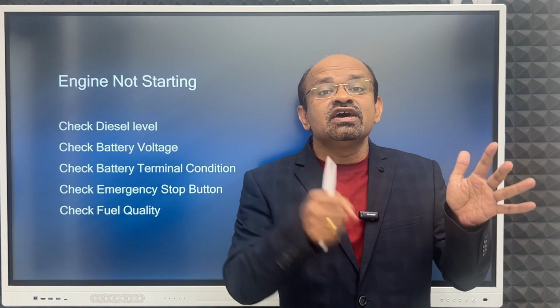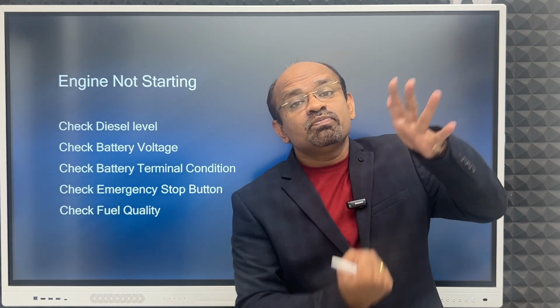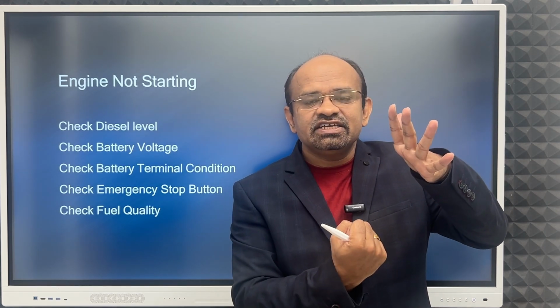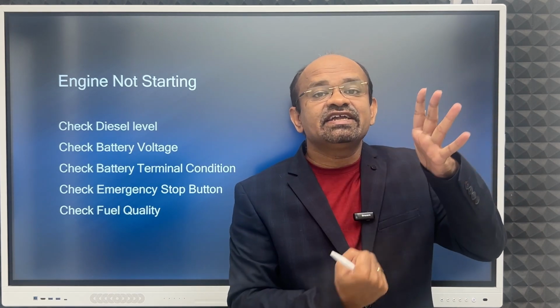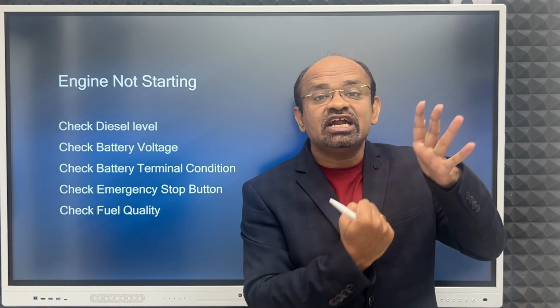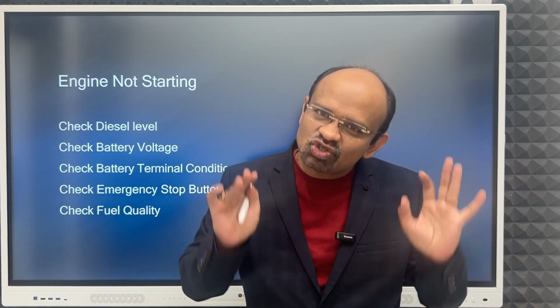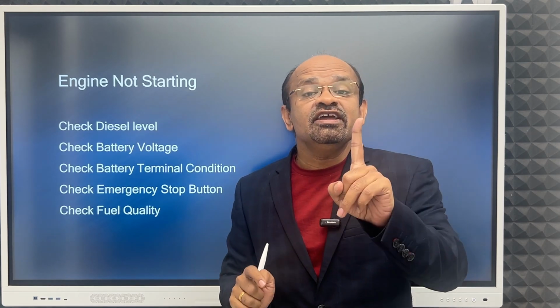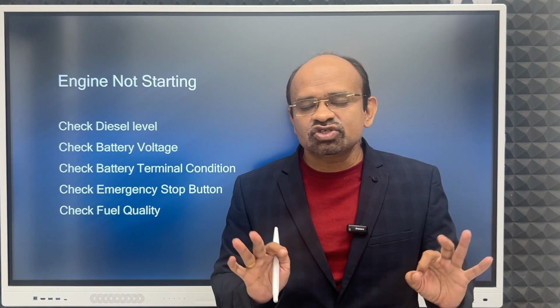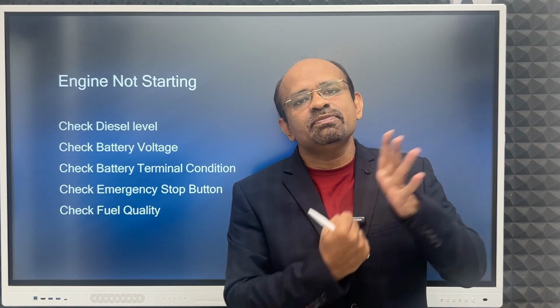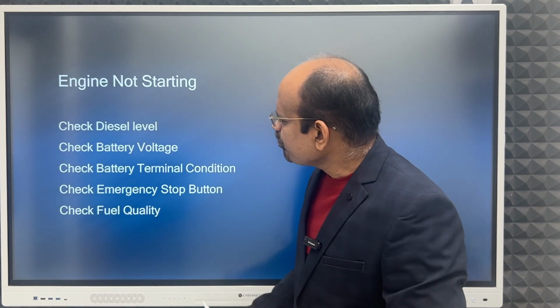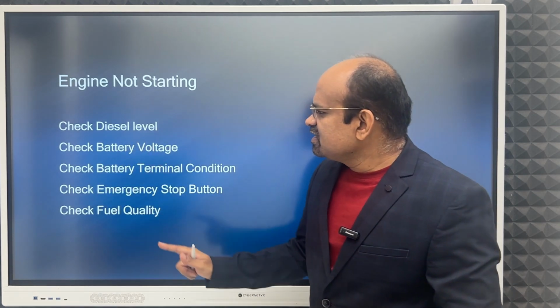It is just rotating the engine and creating that pressure so that blast will start. And once blast is started, nobody can stop it. We have seen it. Only disconnection of fuel supply will stop the engine. Otherwise, it will keep on firing. So diesel level, check battery voltage.